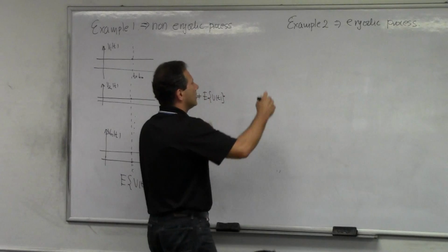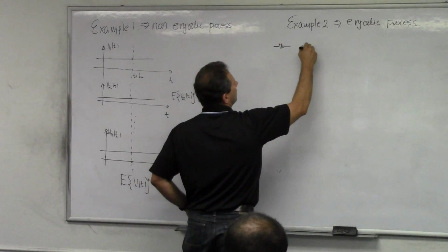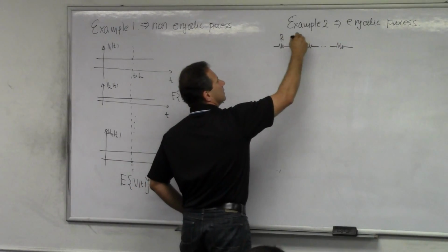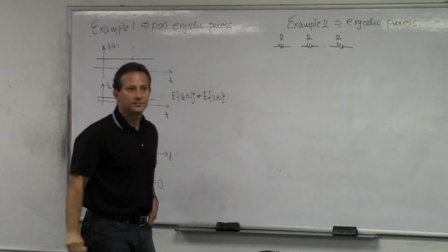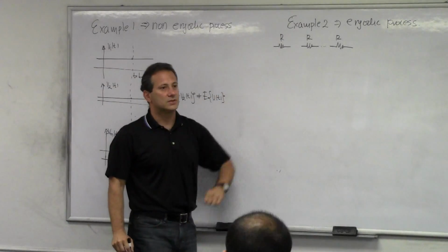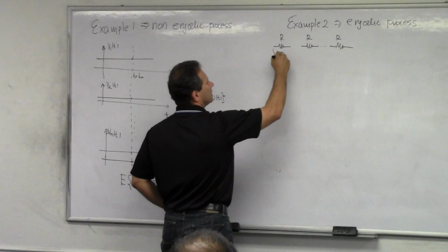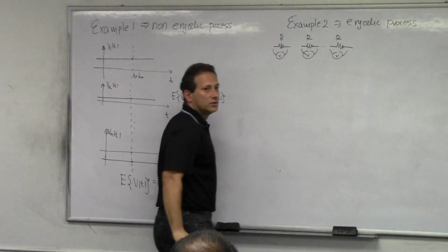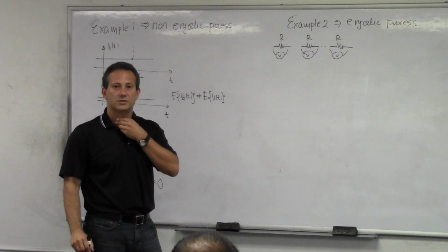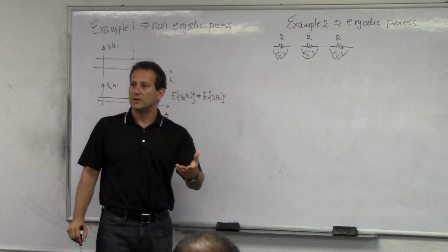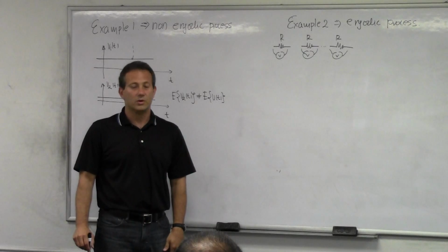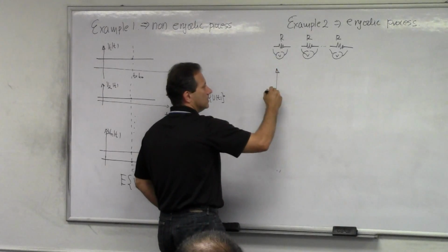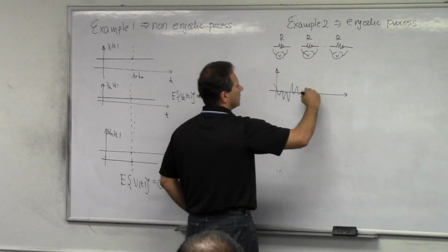Consider a thought experiment where I have, let's say, many different resistors that are all having the same resistance value. Okay? They're all having the same resistance R. And I have a very sensitive voltmeter that I put on the edges of all of these resistors, and I'm measuring the voltage across these resistors. Since the resistors are not at zero temperature, there will be random motion of the electrons going through them. And as a result, at the ports here, there will be some difference in the potential. There will be some voltage. And that would look somewhat like this for the first resistor.